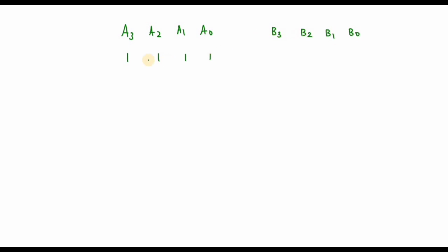If it is shifting by 1 bit, the left-hand side most significant bit is filled with 0, and the rest of the bits are shifted towards right. This is for shift 1 value. Suppose it is shift 2, then 2 bits get 0, 0, and the rest of the values get shifted towards right.